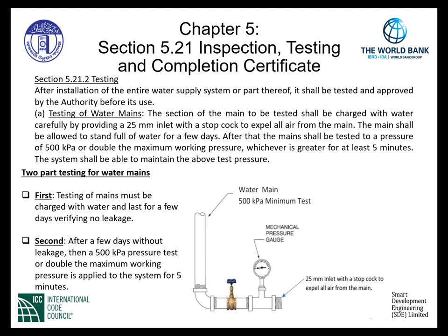The section of the main to be tested shall be charged with water, carefully by providing a 25 millimeter inlet with a stopcock to expel all air from the main. The main shall be allowed to stand full of water for a few days. In other words, we are charging the entire main with water at a static pressure. The main shall be allowed to stand for a few days full of water. We observe at that point to see if there is any leaks in the system.